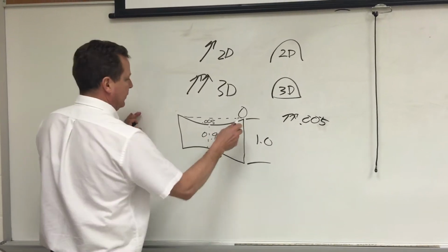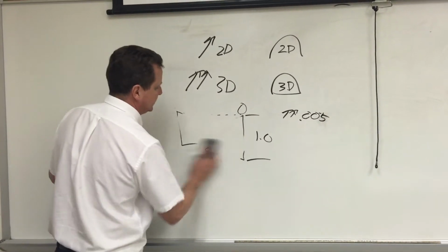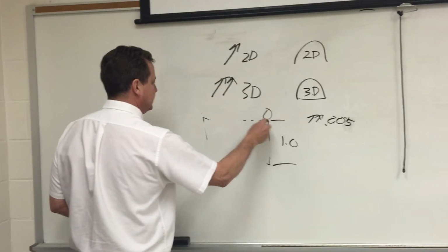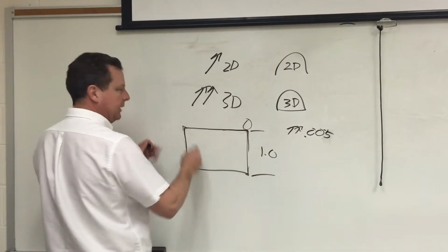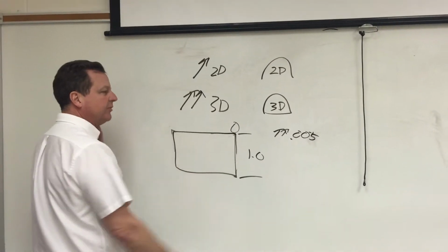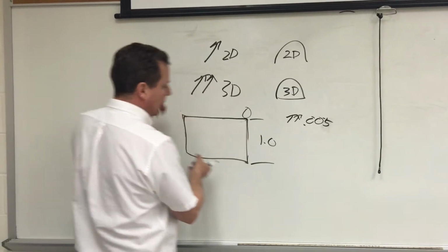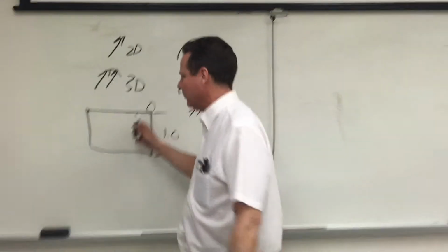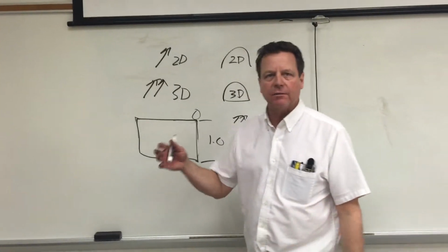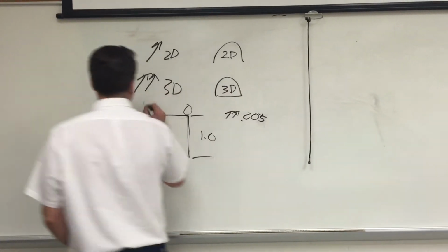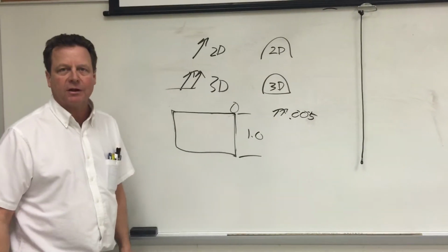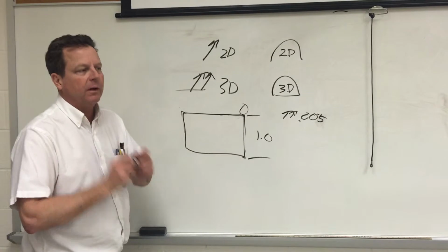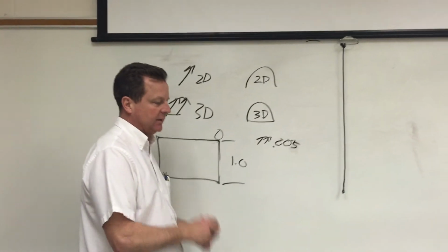So what do you get if you have made this correctly, and this is not the case with total runout? You will also get straightness and cylindricity. You'll get the diameter correctly. There'll be no taper. There's all kinds of other things that go along with total runout that will ensure the geometric tolerancing of the part and its performance in assembly.